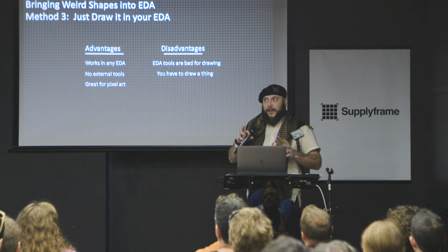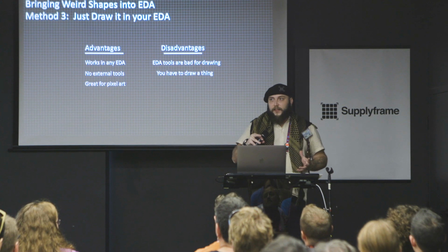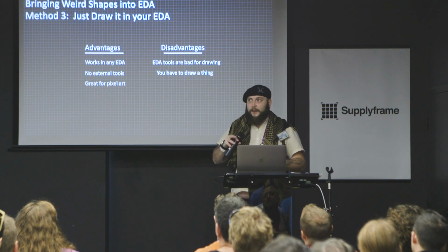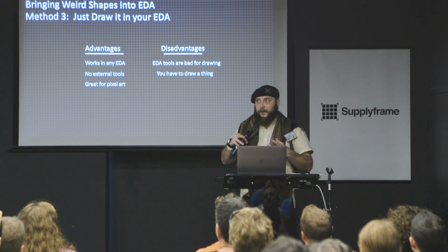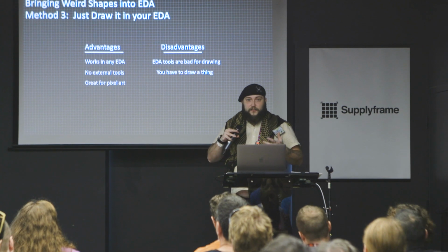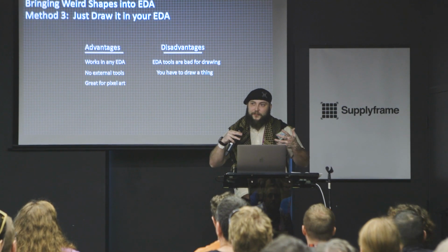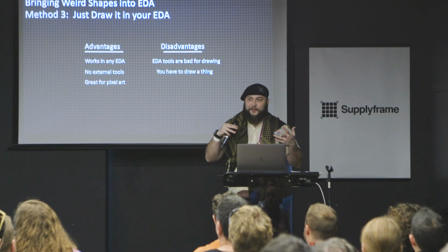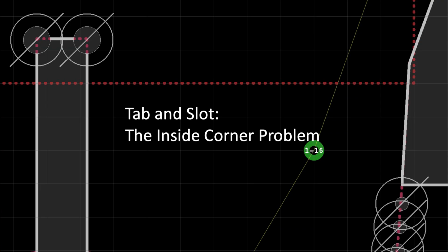Good. Now what? Well, you put those weird shapes into different layers in your PCB, and now you can stack the PCBs together, fit them together, and make things in 3 dimensions. The easiest way to do this is with joinery, like if you imagine you're doing a woodworking project, except you're using fiberglass. The way that I like to do this a lot is with this tab and slot construction, sort of like a cross-lap joint if you're into woodworking.